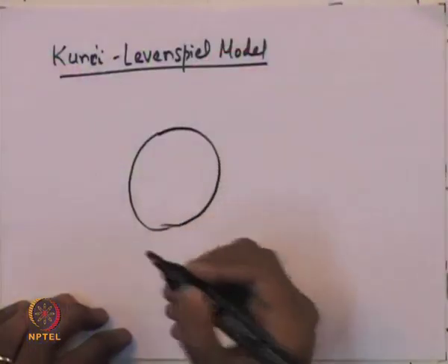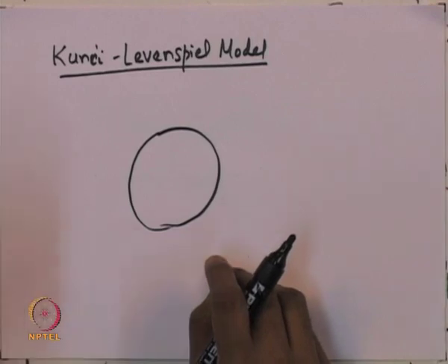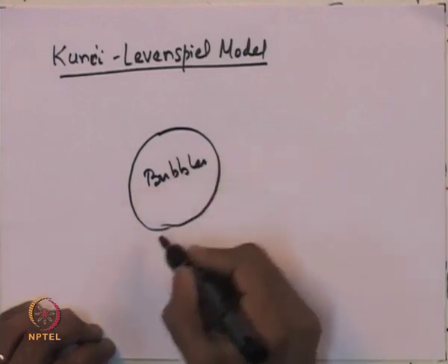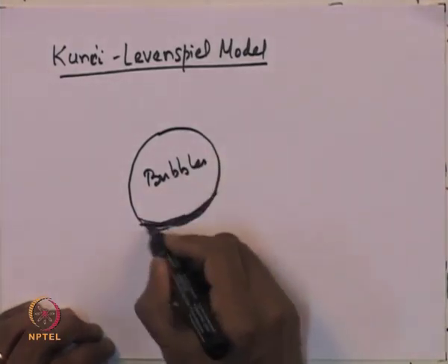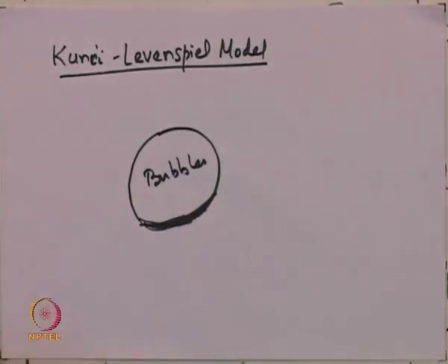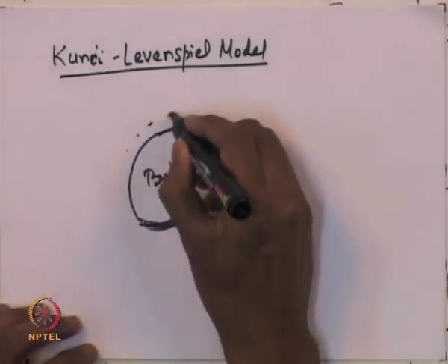It also assumes that the concentration of the solids flowing downwards in the emulsion phase is equal to the concentration of the solids present in the wakes, which are formed just below the bubble. Just to recap, the bubbles are formed as soon as the fluid goes through the bed, and the bubbles carry a certain amount of particles. There is a wake formed below the bubble, where a lot of particles of high concentration are carried along with the bubble. Around the bubbles, there is a phase called the cloud phase.